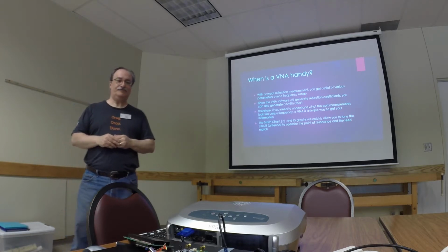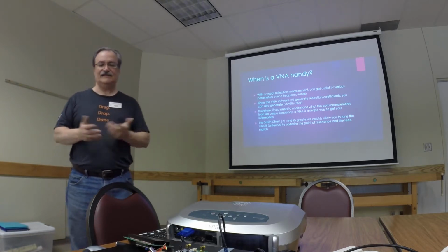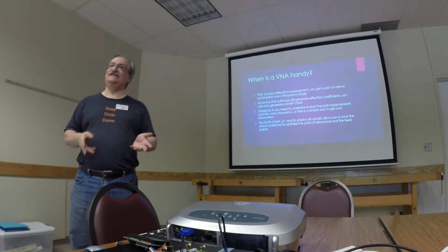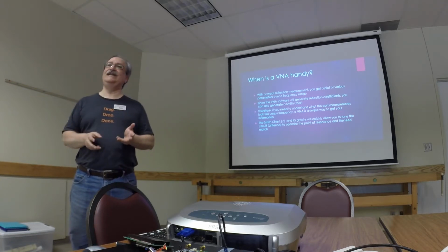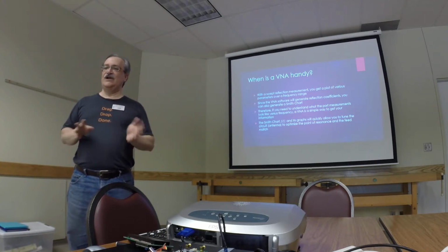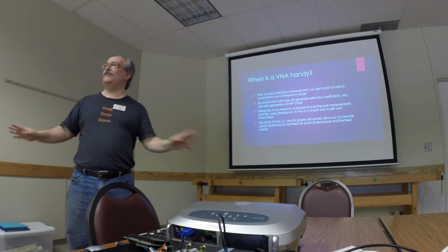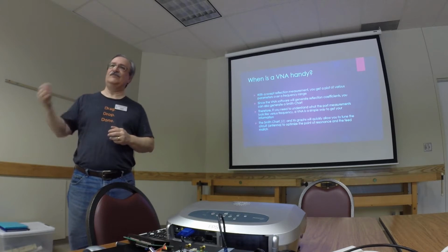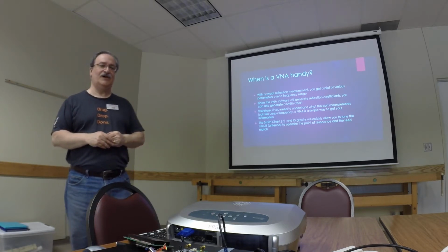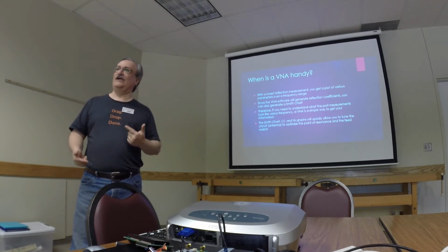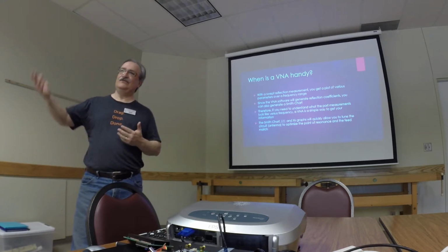I'm one of those people that learned, because I was a service tech, not to have switches on your transceivers, because sure enough, you'll have it in the wrong position, key down, and blow up the other transceiver. So rather than try to keep that straight, I've always just stayed away from it completely and always switched the antennas only. And if I have to physically move coax, I physically move the coax.